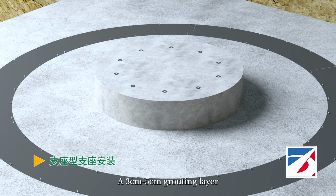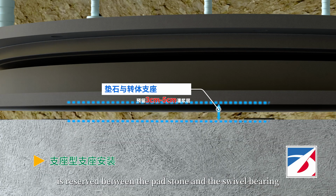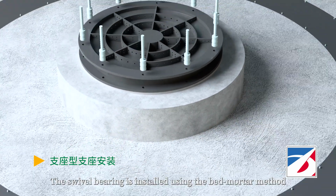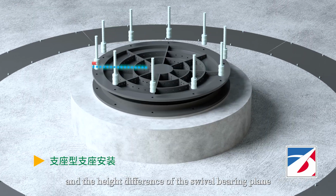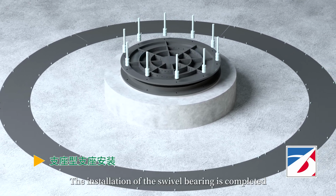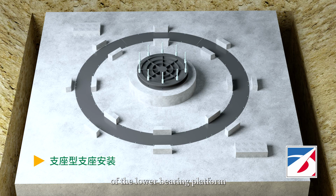A 3 cm to 5 cm grouting layer is reserved between the padstone and the swivel bearing, and high-strength non-shrink grouting material is used. The swivel bearing is installed using the bed mortar method, and the height difference of the swivel bearing plane should not exceed 0.001 rad. The installation of the swivel bearing is completed. The boosting reaction seat and the jack reaction seat are cast to complete the construction of the lower bearing platform.